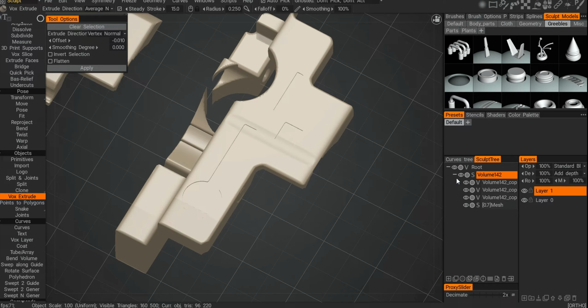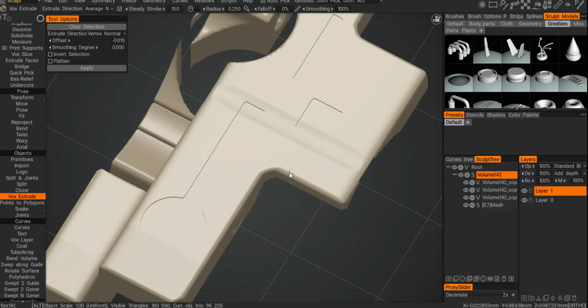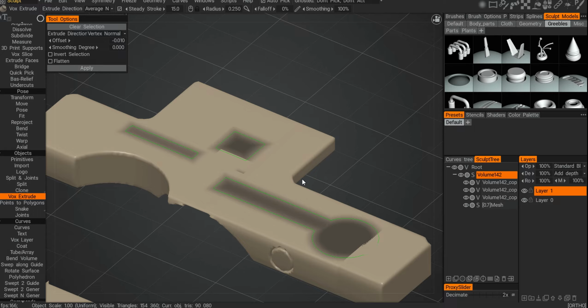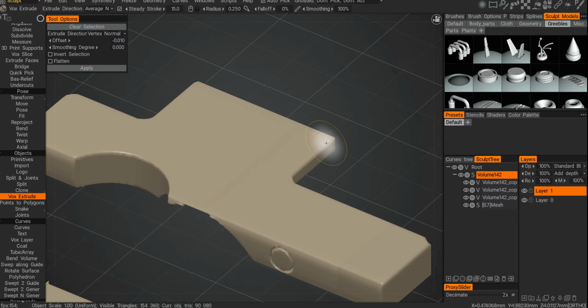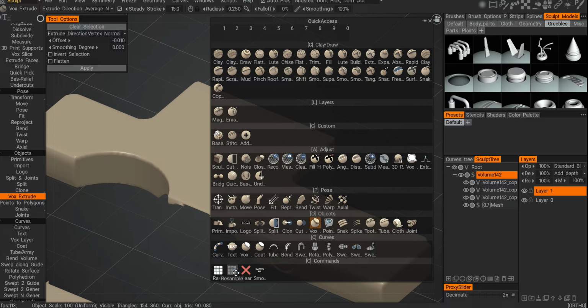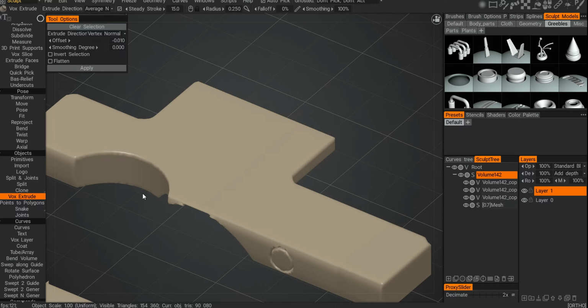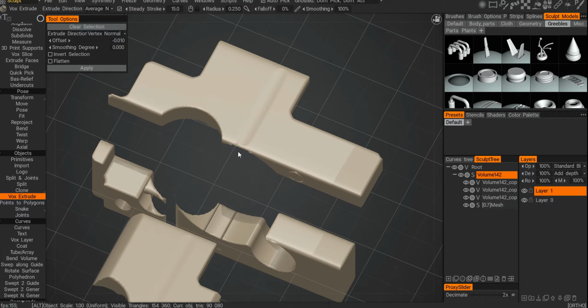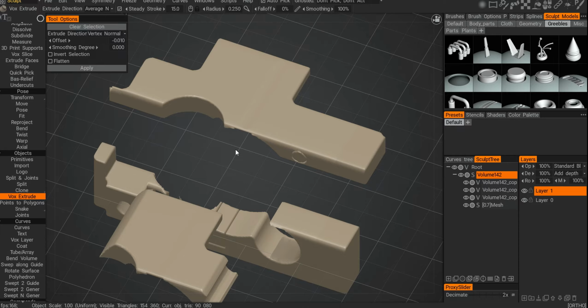This is how you can achieve super sharp edges in your design using this extrude tool. And if I want to cancel out the selection, I'll press Ctrl D. This is my hotkey to resample, and that also allows you to drop the selection. Otherwise, it kind of stays there forever. It's a bit of a little bug inside 3D Coat.